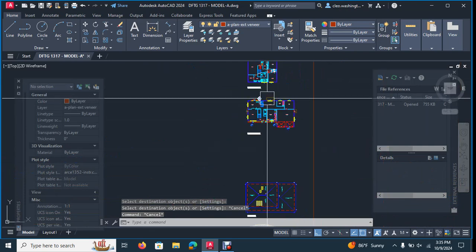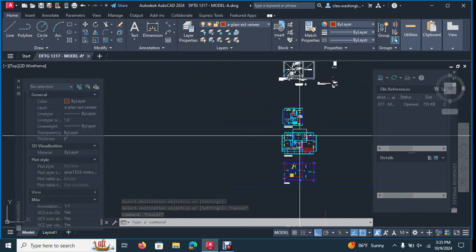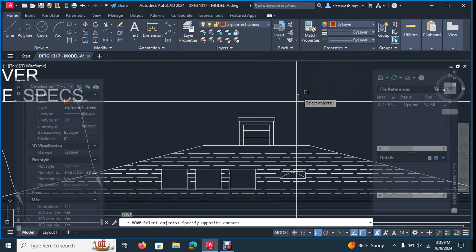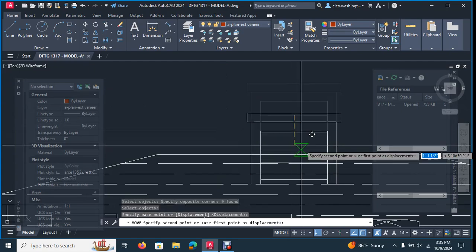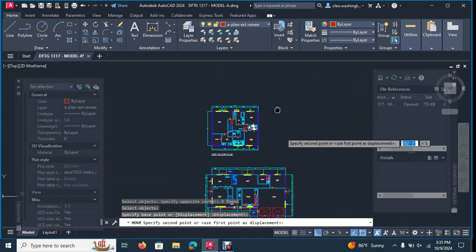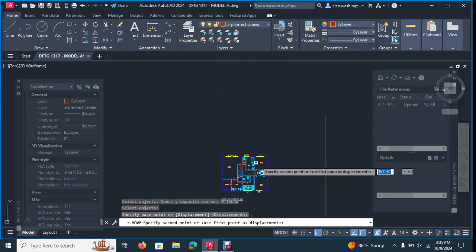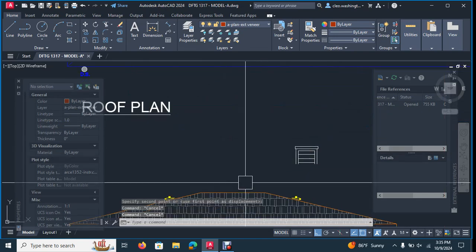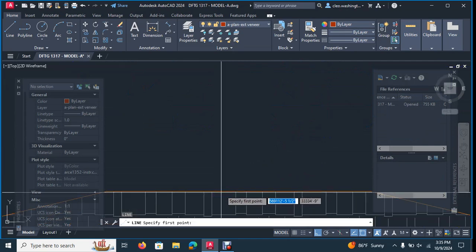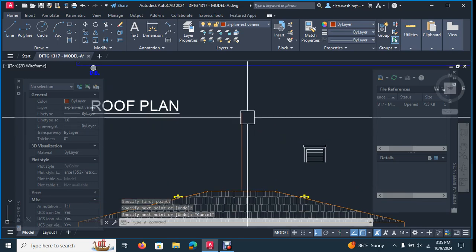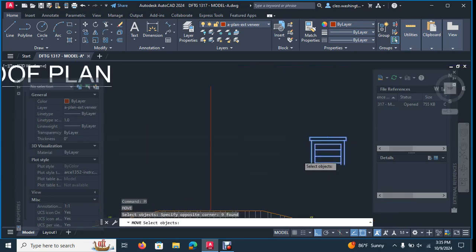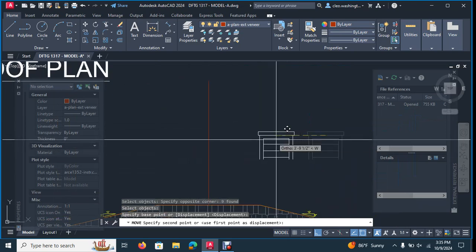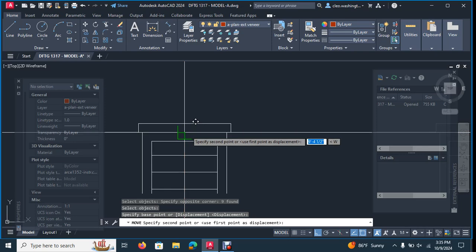And then you can just take the chimney that's shown here, okay, and just copy it down, and you can just put it on the layer. You don't have to redraw this, you can just copy it down. And if you had to redraw it, you could do that, right? So let's go ahead and draw a line from the center of this line. And let's take the roof, grab the center of the roof line, which is right here, align it with this line.